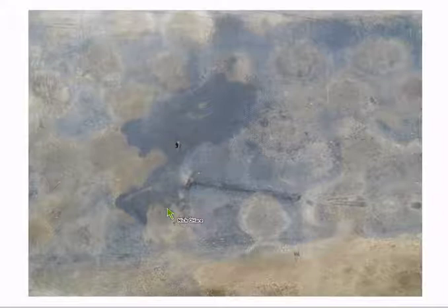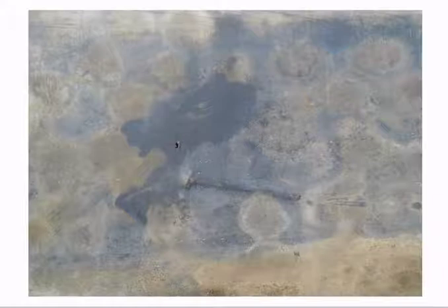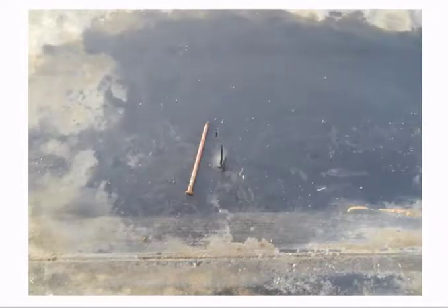So here you have a hole in the membrane and what looks to be a screw or a nail underneath that membrane, and that's pretty common when people put on these types of roofs. They'll get a screw or a rock stuck in their boot and walk across the membrane, and it just falls off their boot and they don't see it and they roof over it. Well, over time, with that membrane shifting back and forth, shrinking and expanding with the seasons, you'll wear a hole in that, or just foot traffic on the roof.